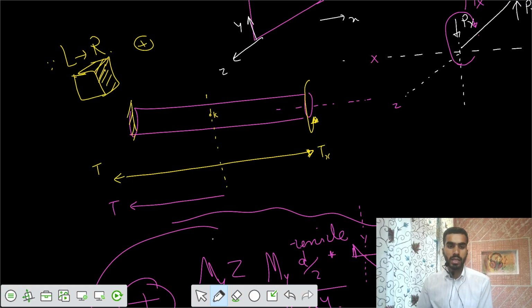I would say there's some T. So your resisting torque at the point K, that's your resisting torque. So that means, how can you show this in terms of an arrow, clockwise or anti-clockwise? So I would say the thumb is pointing away from the section, so that means there should be some anti-clockwise resisting couple, anti-clockwise.